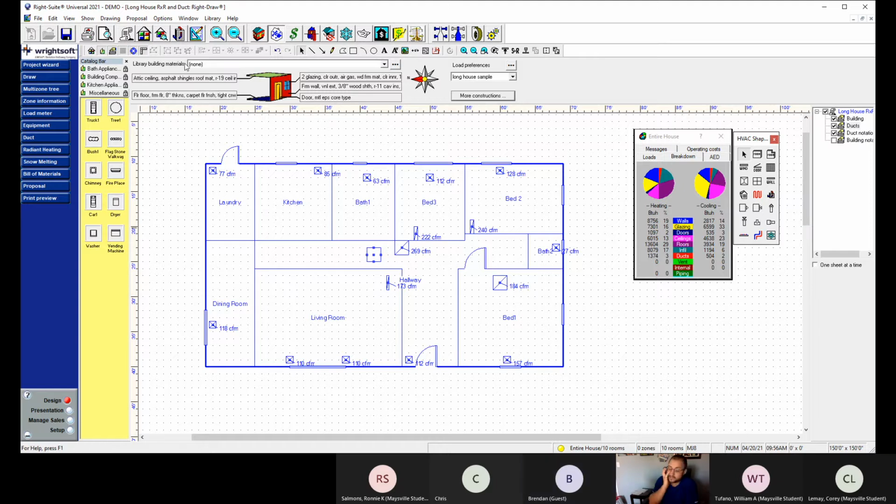So I did put a video on last night. That was me kind of going through a duct layout and how you would size that based on CFMs in every room, every 4 feet you're putting a piece of duct. My numbers were off because my load was off. Now I figured out what the deal with my load was. So when we get back to class, we can use this new load and this new breakdown.